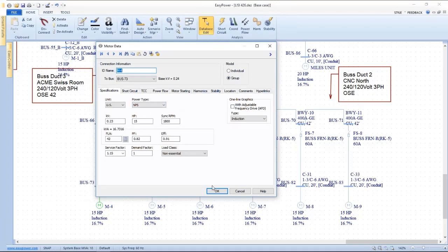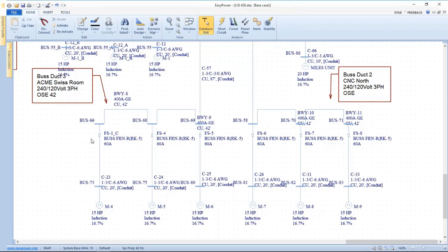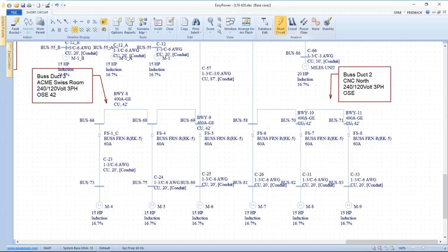And so the same discussion applies as to, okay, if we've done a group modeling, what are we going to use for the protective device? And in that case, at least I would argue or suggest I want to use the largest single breaker because that would have the greatest amount of let-through to give me the calculations for downstream energy.